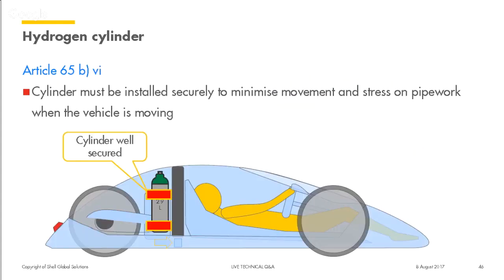For hydrogen cylinders, next slide, please make sure that the cylinder is well secured and in such a way that there's no movement and stress on the pipework when the car is moving.